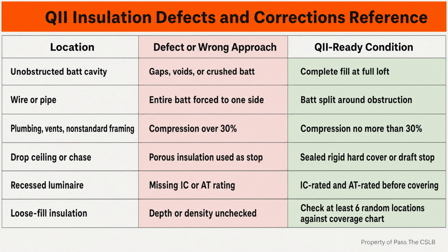For the General B contractor, the practical supervision point is to verify the specialty contractor safety program before mobilization, rather than discovering a missing program during application. I do not select cartridges or conduct medical evaluations unless I am qualified and responsible for that program. I confirm that the responsible employer has the required system in place and that site coordination does not expose other workers to the operation.